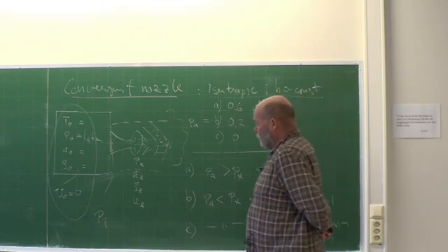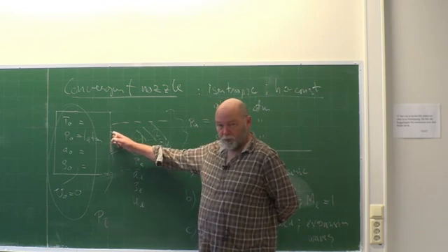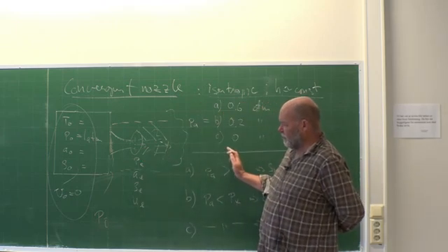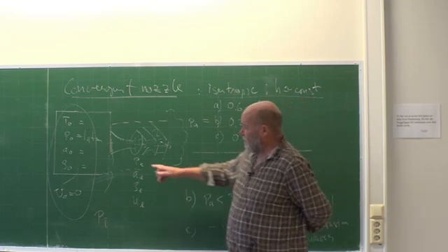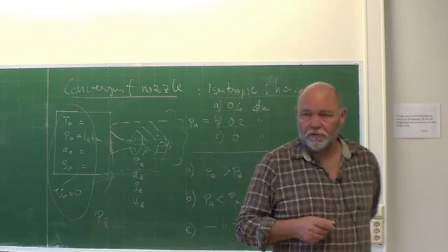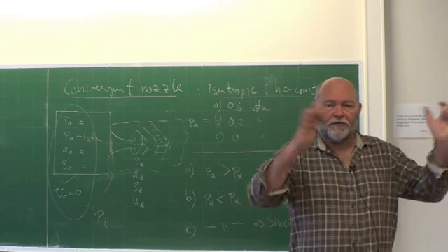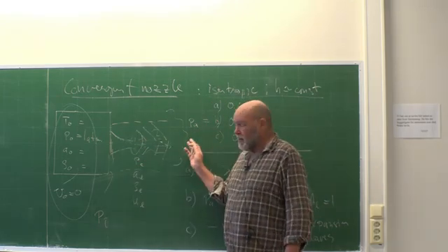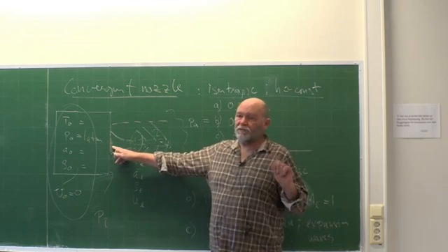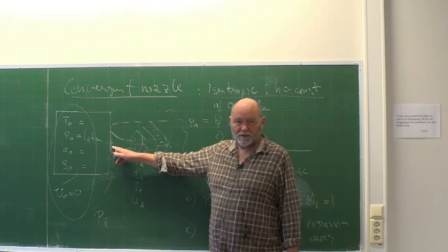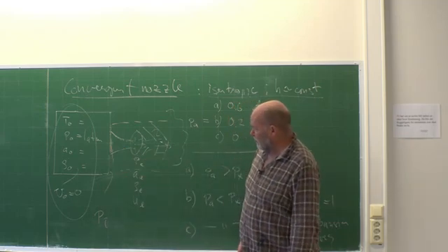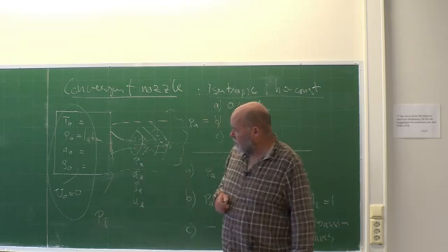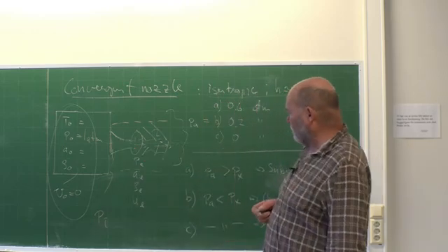And for the boundary conditions in this problem, you have to put in this pressure inlet. You have to put in the reference pressure here on the outside. And then velocity, well, zero gradient. I mean, you are giving the driving force, so the velocity is going to be a part of the solution. You can't put a driving force, a pressure difference, and a constant velocity here. That's not good. Then you're strangling the code. That's too much information. So you have to give it freedom to find the correct solution by itself, hence zero gradient on the velocity. Okay, fair enough.